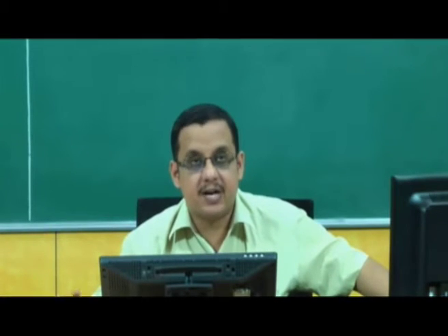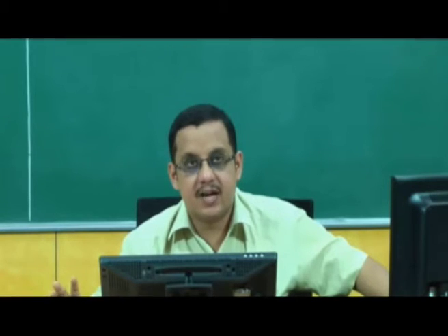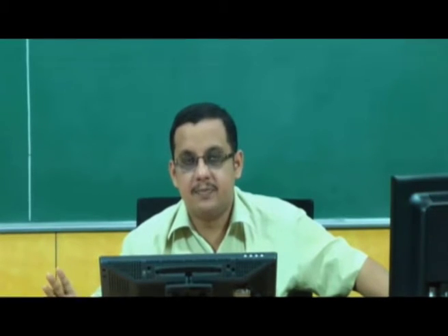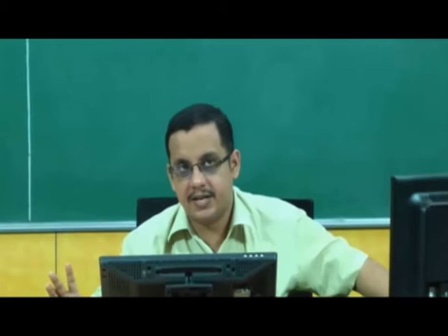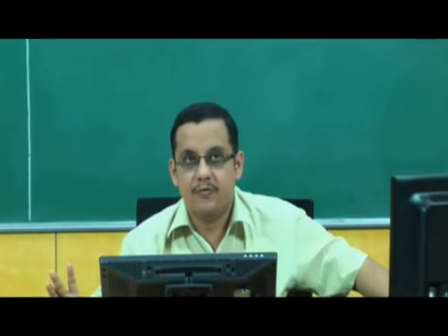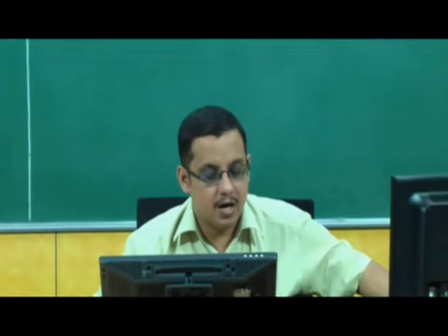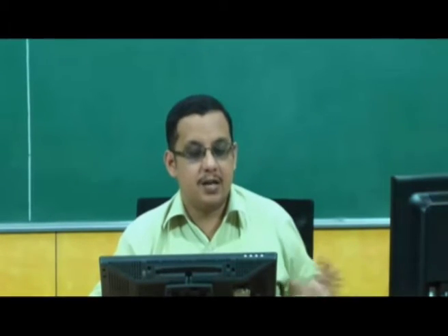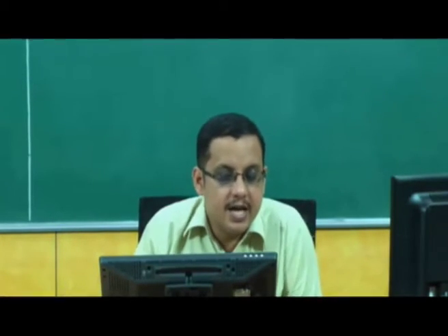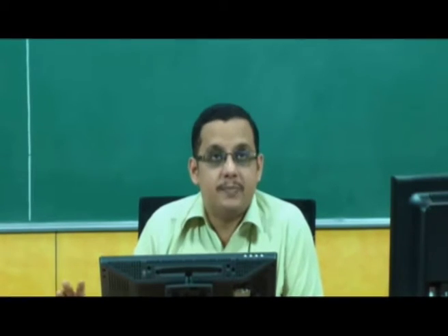This is a figure taken from Shigley. So some books are actually showing this carefully, that the base circle can either be larger or smaller than the dedendum circle. There is no rule which prohibits either of these alternatives. So, to answer your question, BEC, the base circle is not always taken below the dedendum circle.